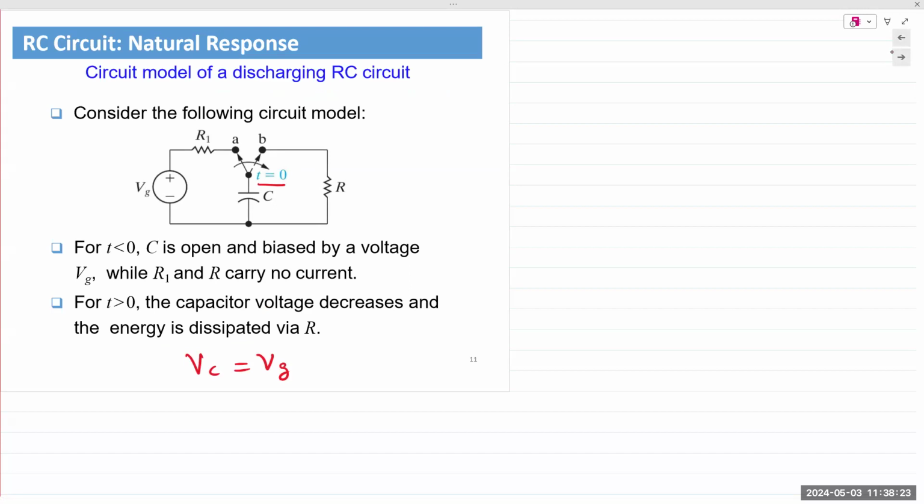It does. That's why we have the time constant, R times C. That simply slows the rate. Basically, if R is smaller, then current is higher, so it charges faster. If R is big, then it takes longer to charge, current is slower. When it finishes charging, it acts like an open circuit. So again, R does have an effect.